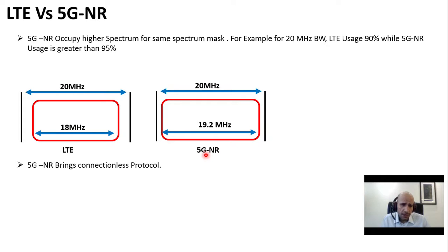That's why you will have more throughput in the downlink direction in the same configuration between 4G and 5G. Think about having the same 20 MHz bandwidth in 4G and 5G, with, for example, FDD 20 MHz, 4x4 MIMO, 256 QAM, and subcarrier spacing of 15 kHz in both LTE and 5G.